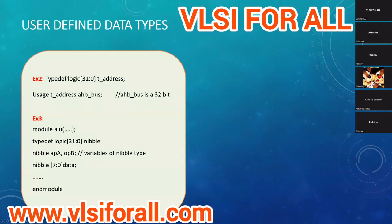So you can create your own data types, typedefs, to actually model what the design is doing, the intent of certain signals or certain FSMs. Let's say there's an FSM to model the different states of a lift. A lift goes up, down, and so on. To model that, you can say it's in idle state, or busy state, or working state. So you can give those special names to them.